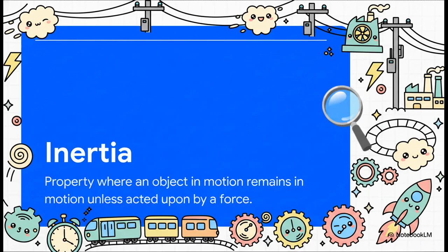The secret to that balance has always been mechanical inertia. Traditional power plants, coal, gas, nuclear, they all use massive, heavy, rotating generators. Those spinning turbines provide physical inertia. They're essentially mechanical shock absorbers. If a power plant trips offline, these heavy turbines keep spinning for a moment, injecting just enough emergency power into the grid to keep the voltage stable while the entire system recovers.